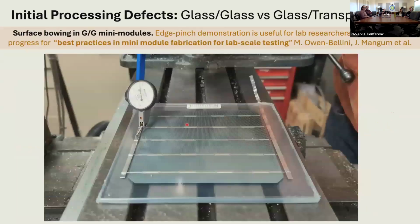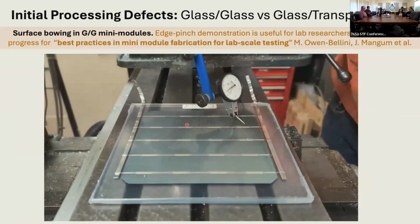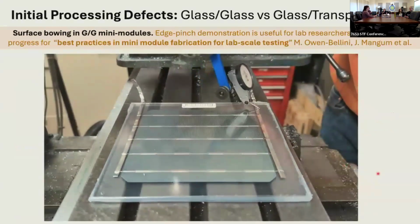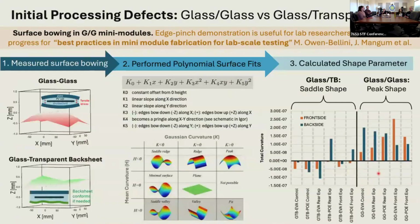So I drew these glass samples as being kind of a bowed shape, and we do characterize that to show that that's actually the case in these mini modules. So this is how we do that using some machining tools. And then once we have that data, first, we measure the surface bowing like I showed you in that video, and then perform polynomial surface fits to these samples to kind of understand their shape parameters. Then you can calculate an overall shape parameter for the sample based on these surface fits.